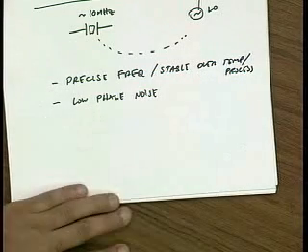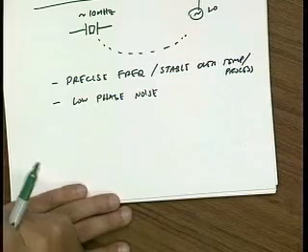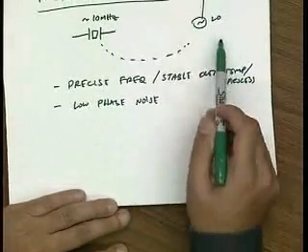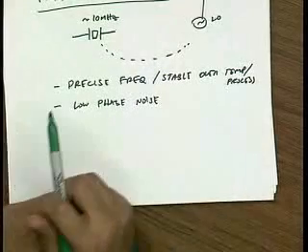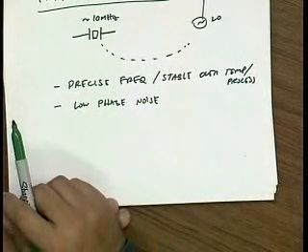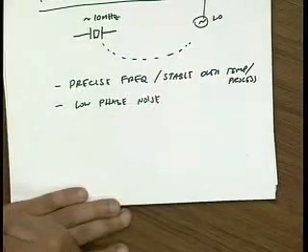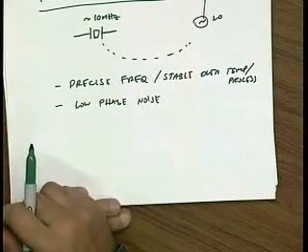We also need low phase noise. We talked about phase noise last lecture. The phase noise that you would get out of a low Q oscillator often is too high to use in especially narrowband circuits. We had the issue with spectral leakage. We also had the issue with reciprocal mixing.